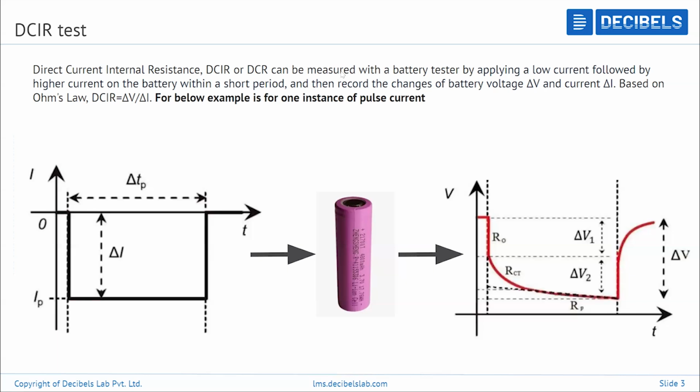Here, the equivalent circuit model you can take as Thevenin. I'll try to draw it here. It need not be only Thevenin, it can be anything. You can attach more RC blocks. So this is R1, C1, and R2, and you can attach n number of RC blocks. This can represent your Thevenin circuit because of one RC pack. The cell behavior will be captured with these elements, resistors and a set of RC blocks.